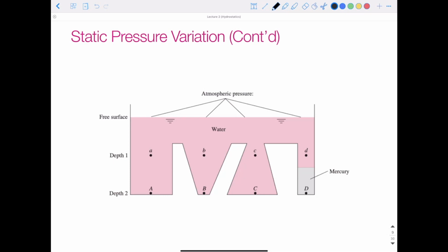So we can write, if we look at the left-hand side over here, we can look at the pressure distribution for a water column going from the bottom to the top. And the pressure would increase from the top, and it would increase linearly. And the slope of that increase would be equal to the specific weight of water. So if we were to just draw this, this would be the pressure distribution as we would travel further down this column.